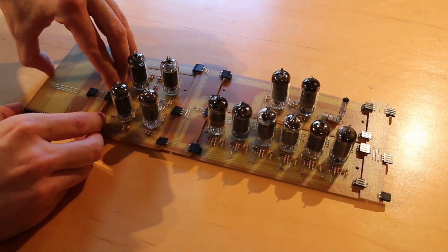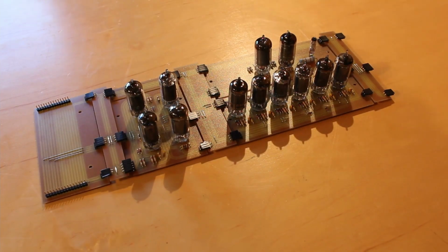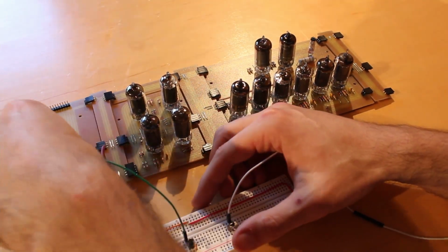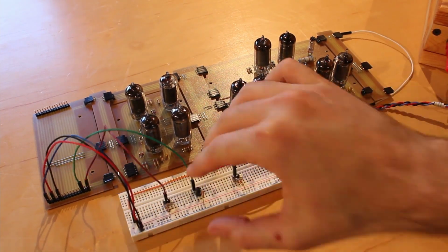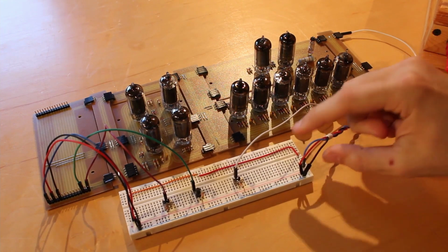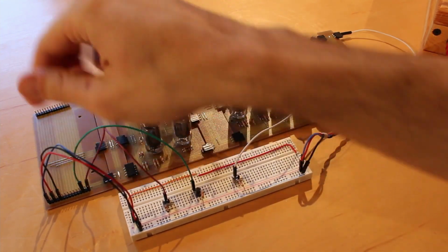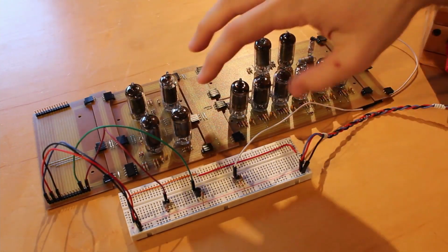All right, so I think we're in a pretty good place to give this a proper test now. But there's still a couple things that we need to actually hook up in order to do the test. So I'll go ahead and hook up my breadboard here for that. All right, so our breadboard is set up pretty simply. We have our ground power and minus 12 volts coming in here, and then that goes through these jumpers over to the main inboard here that's going to end up powering everything here.